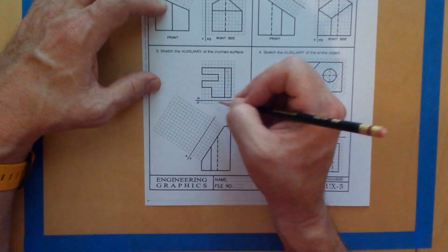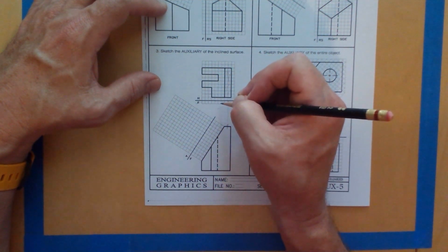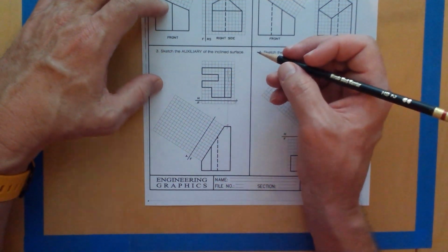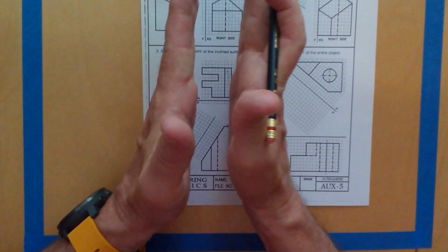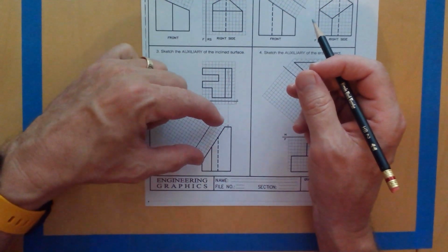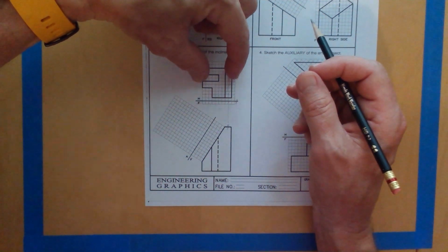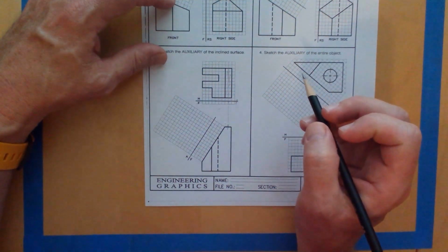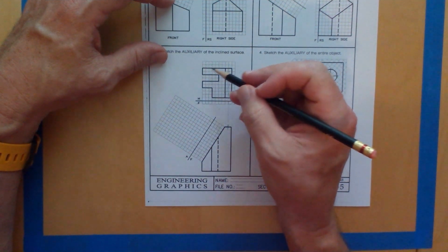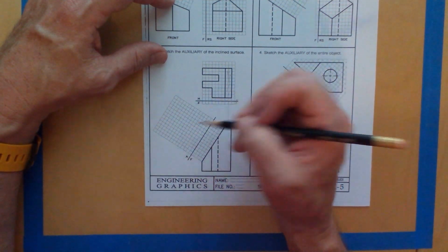And so therefore we call this projection of the inclined surface, in this case, foreshortened, right? Because basically it's scrunched in this direction. It's squished this way, right? So normally it's this long, but because we're projecting it up like this, it's this long. But that being said, the general outline or shape of the object is still going to be the same, right?